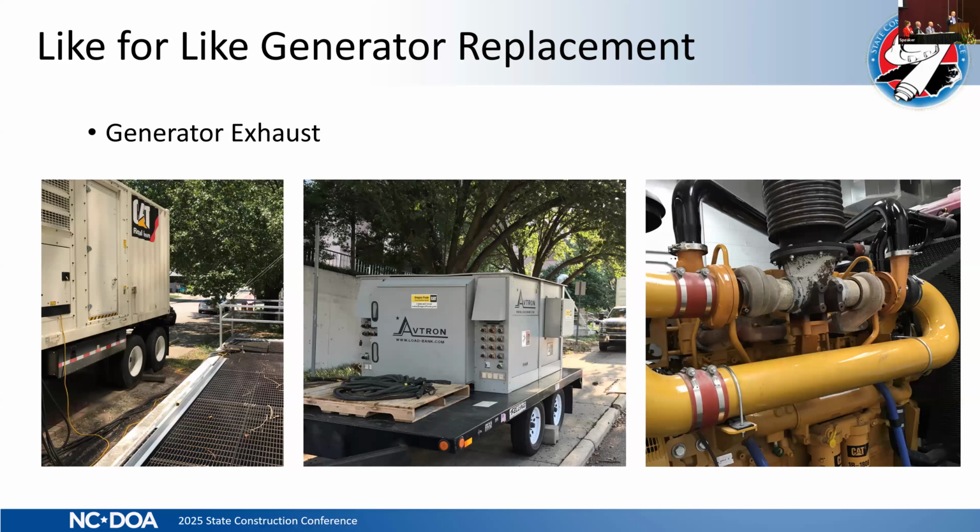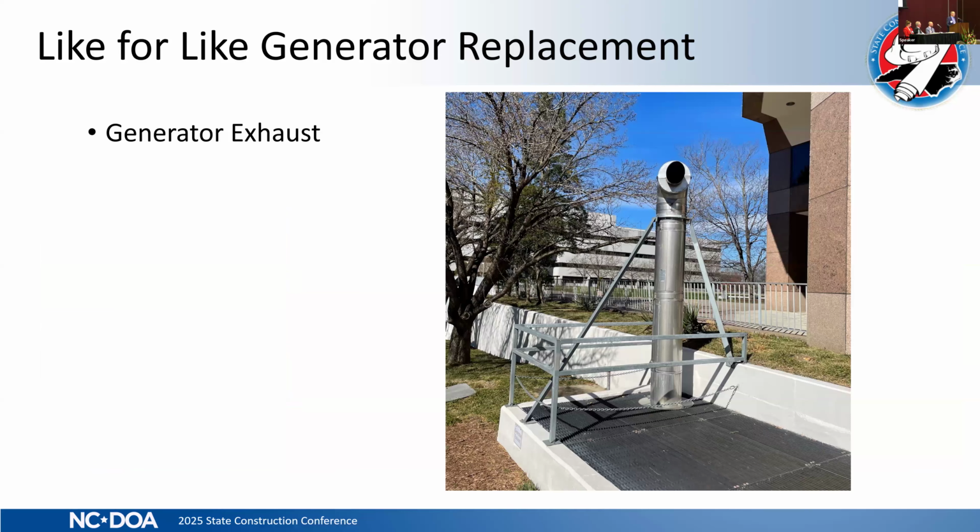Although the exhaust was not in the walkway, the proximity and the high temperatures gave us concern for a safety risk. So under the same emergency project, we reached out to a mechanical contractor to help us with a generator exhaust modification. We went with a double wall insulated exhaust vent. So same pathway leaving the building, but instead of turning down, it turned up. It went through that grate and extended above. And you can see here, some people call it the snorkel.